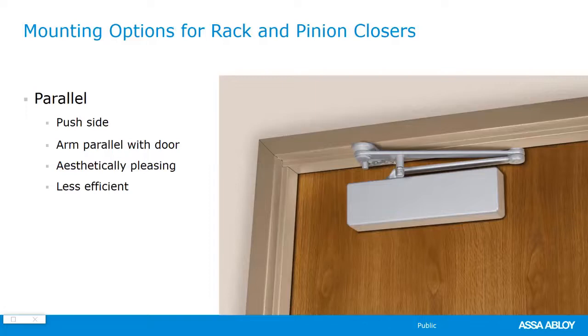Maybe they meant to template the door closer to 180, but they only templated it to 110. Well, you've got holes drilled in the door. There's not a lot we can do without moving the door closer. And if it's fire rated, man, you're in trouble, because we have to figure out how to get that door recertified if you're going to put new holes in it. So we've got some issues. Door closers are one of those things that you just can't throw on a door without reading the templating.